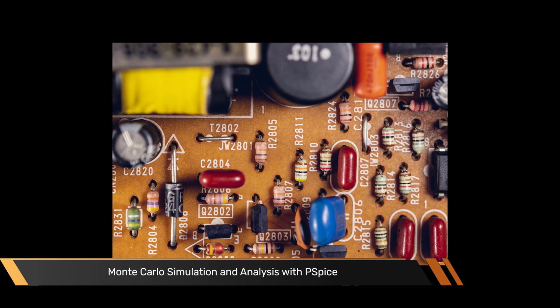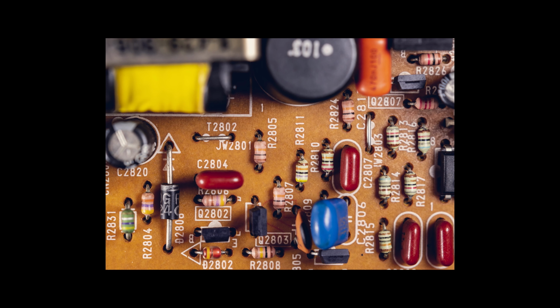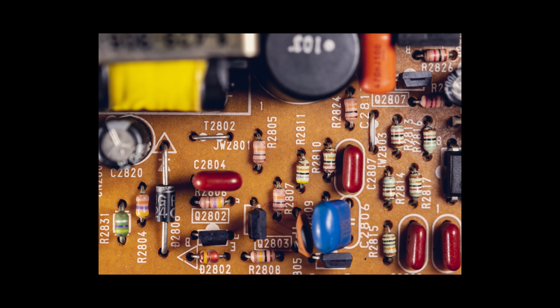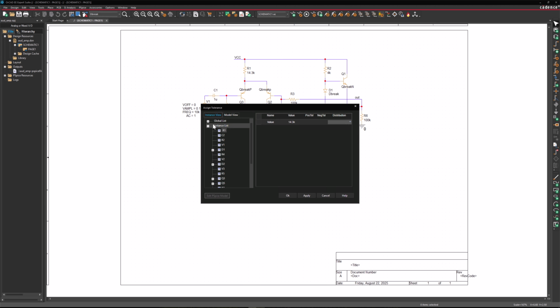In PSpice, you can perform Monte Carlo analysis to randomly vary the component values within its set tolerance range to get the circuit response and statistical data. To perform Monte Carlo analysis in this amplifier circuit, first let's define the tolerance for all the resistors and capacitors in the schematic. For this, launch the Assign Global Tolerance dialog.